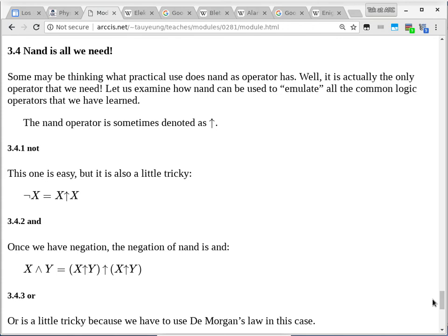But this is the part where we can be convinced that starting with a NAND gate, we can do everything else. In mathematics, this is negation. The little symbol is negation, which you know as the exclamation point symbol in C++. This little up arrow thing is representing NAND. So I'm going to claim that the negation of x is x NAND x. Does that make sense? What if you're not convinced? What are you going to do? Make a truth table. Exactly.